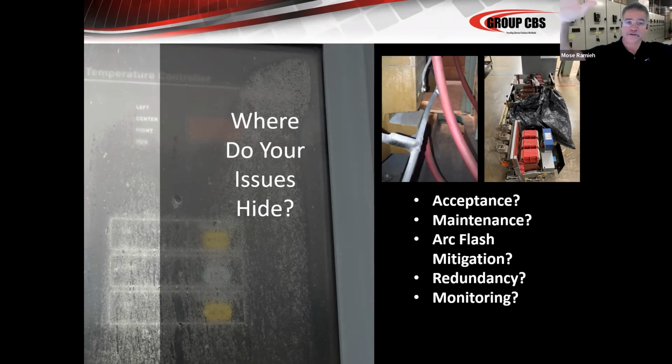There are other technologies out there, and it's amazing some of the technology. There's arc quenching gear now. Similarly, the system recognizes when there's an arc event, and it throws a bolted fault onto the system to basically operate the protected devices even faster. So quenching that arc or eliminating it really before it can ever get started is another example. I shouldn't call that arc resistant. That's arc quenching type gear. And I guess I should add that arc resistant gear is obviously much more expensive than your standard stuff because of the way it's constructed.